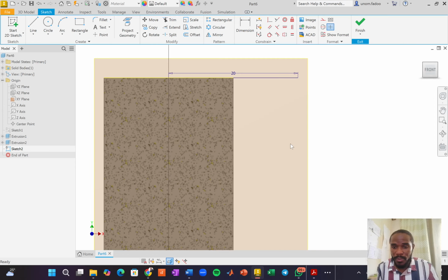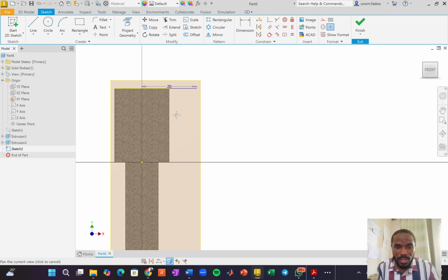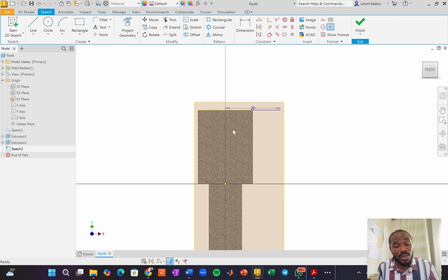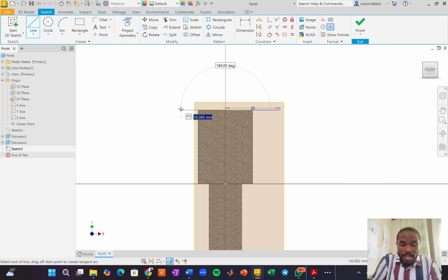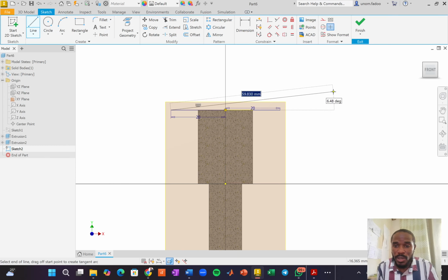Okay. Now, having drawn that, sorry, this is dancing around. I now need to draw the circle that is meant to touch this. Actually, I will need this second aspect of this line before I delete it, because I will need the circumference of my circle to be coincident to both of these. So again, this is going to be 20 and enter. Okay, right click, and I'm happy with those lines.